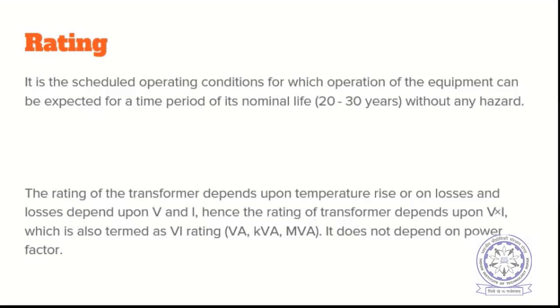Sir, it's exceeding current. Yeah, exceeding current, not exceeding voltage. So overloading means I is increasing. If I increases, losses will increase and consequent effects will be there. Temperature will rise, and therefore what is going to happen? That we have to understand now.